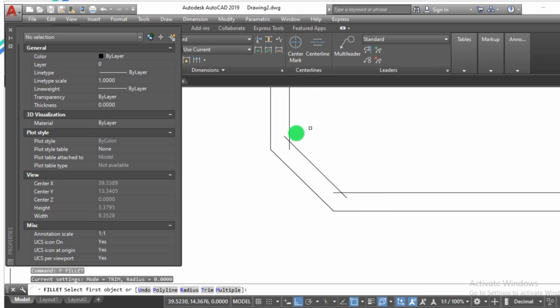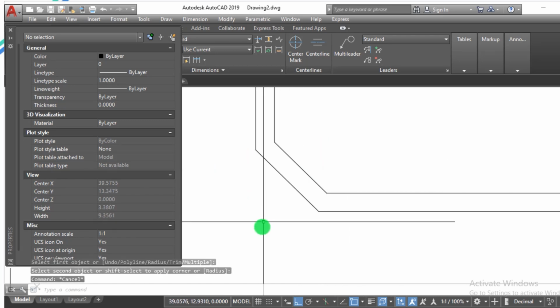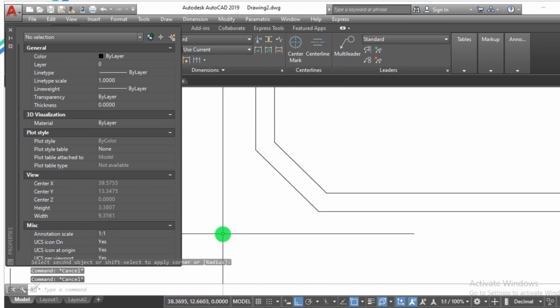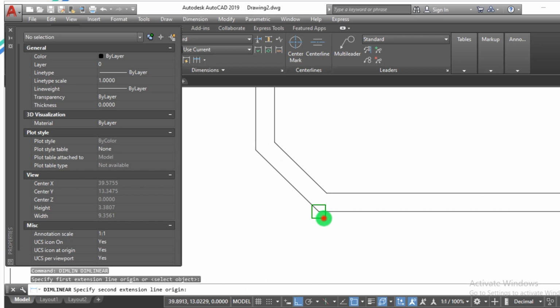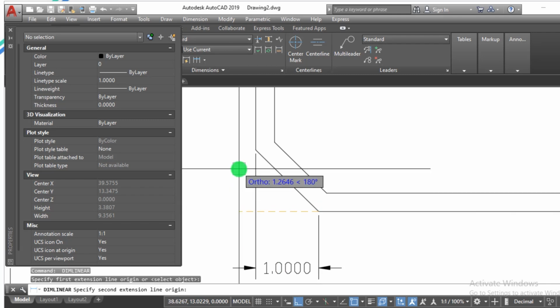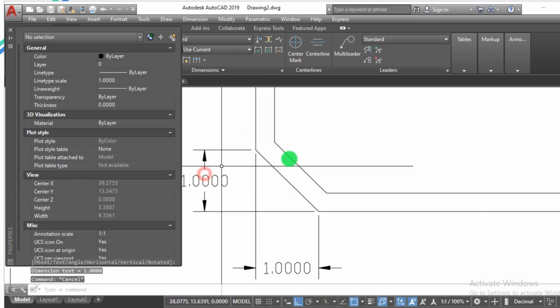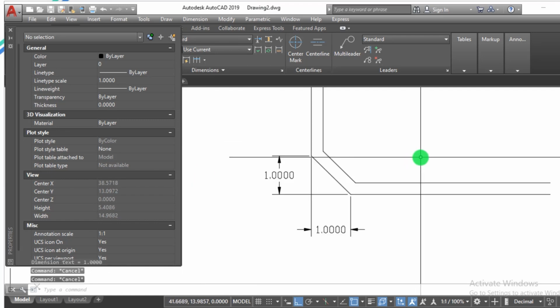In my drawing, I want to show how the chamfer is placed, so that the people who will be working on it can understand how the chamfer can be done. For this, I would give the dim linear, in which I would say this is the x distance, and this is the y distance. So this is how the linear dimension works. So linear dimension, to conclude, is when you want to dimension horizontally or vertically.